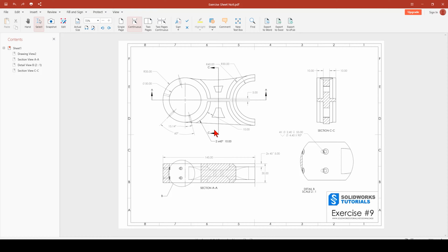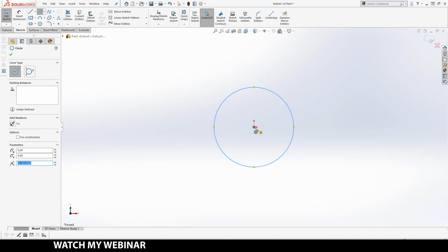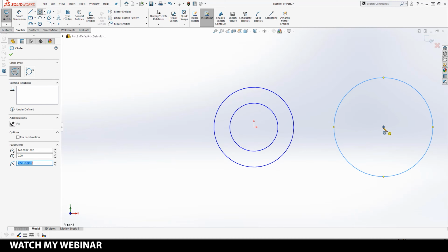I would love to start my drawing by putting one circle in the center. So if I was doing this for the very first time, even though this was not the case when I created this part, I would place this circle on the coordinate system. So I see one circle here, then a half circle on the other side on the right, then I will see some tangential lines. By the way, these two are tangentials, and we will take it from there. So let's do this. Draw two circles here and two half circles here.